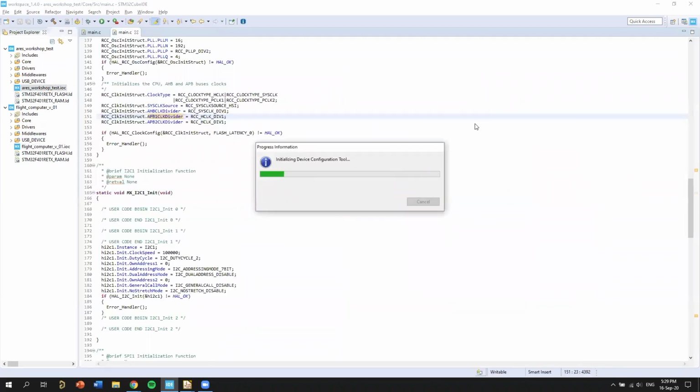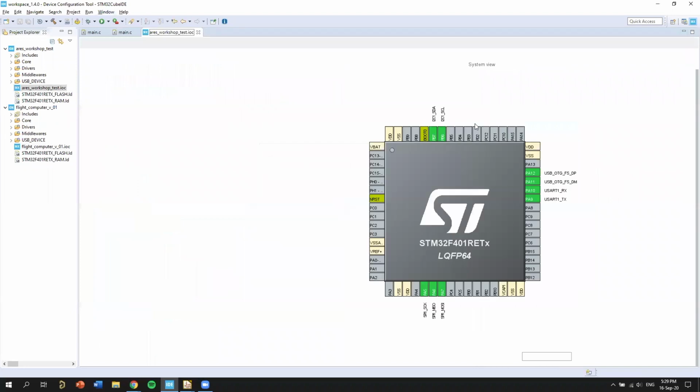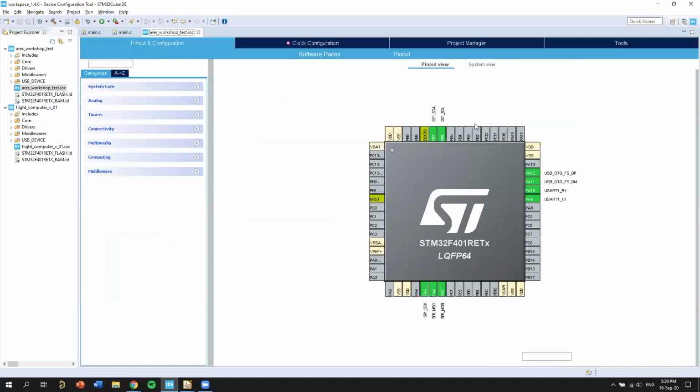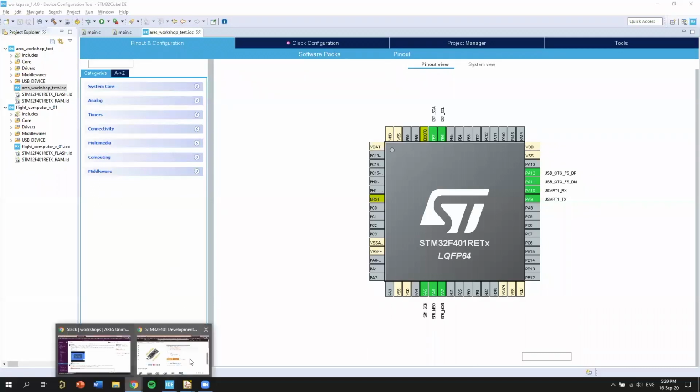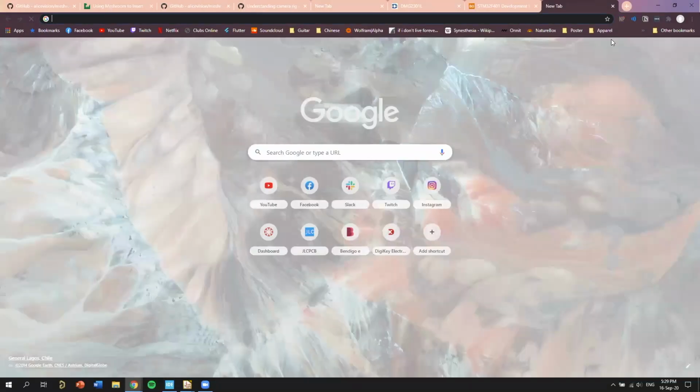obviously, when your chip arrives, the annoying thing is you can't program it for the first time over USB. We need to inject that code into it using an STM32 programmer. And if you remember, it's called an ST-Link.